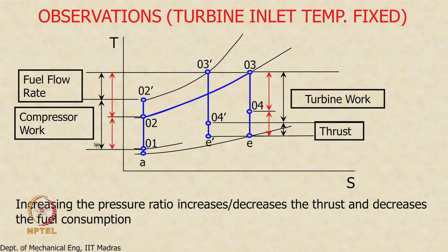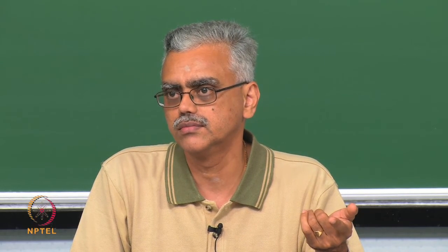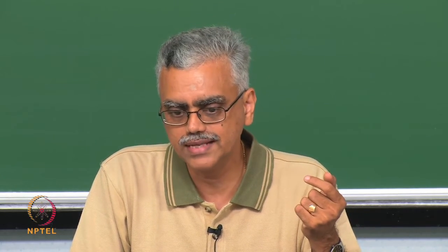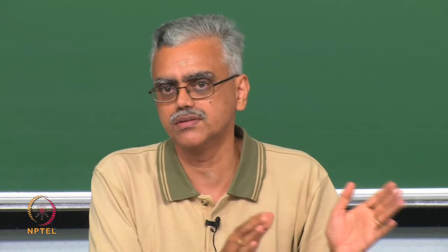So we get the exit state by equating the work from the turbine to the compressor. The exit state of the compressor is known because I know the cycle pressure ratio, but the exit state of the turbine is determined based on the amount of work that we extract from the turbine. Remember, the pressure ratio is only for the compressor, not for the turbine, right? Any other questions?